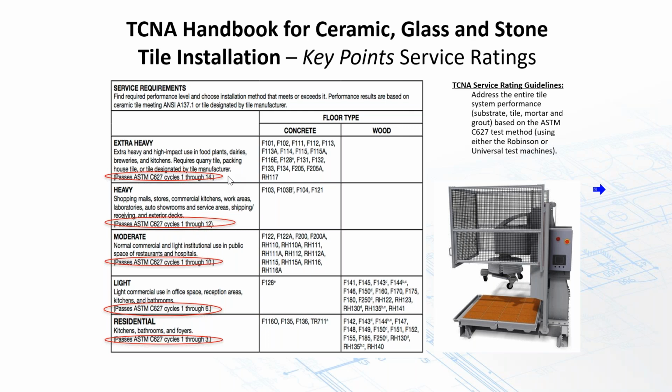For porcelain tile direct on concrete, you would anticipate it going all the way through the testing, and it's surviving that testing very, very well. As opposed to if I had a gauge porcelain tile with a minimum of 4 grout joints in it, and I installed that over, let's say, a peel and stick rubbery membrane that's used for crack isolation, I would not anticipate that going all that far, maybe light commercial or residential for that matter.